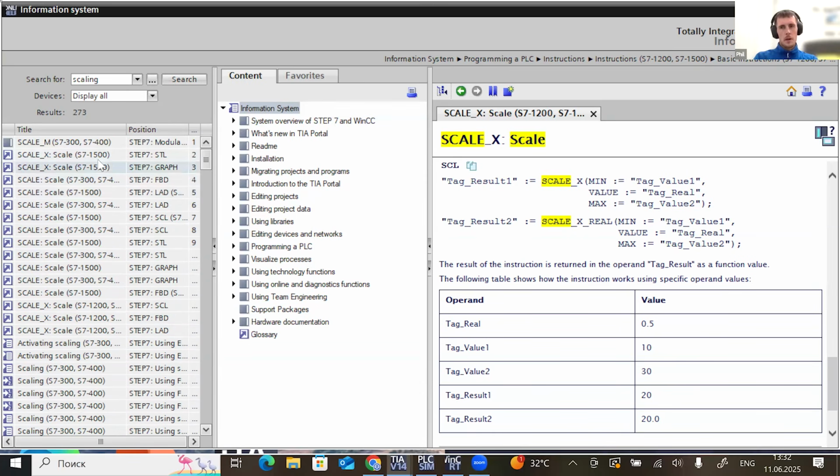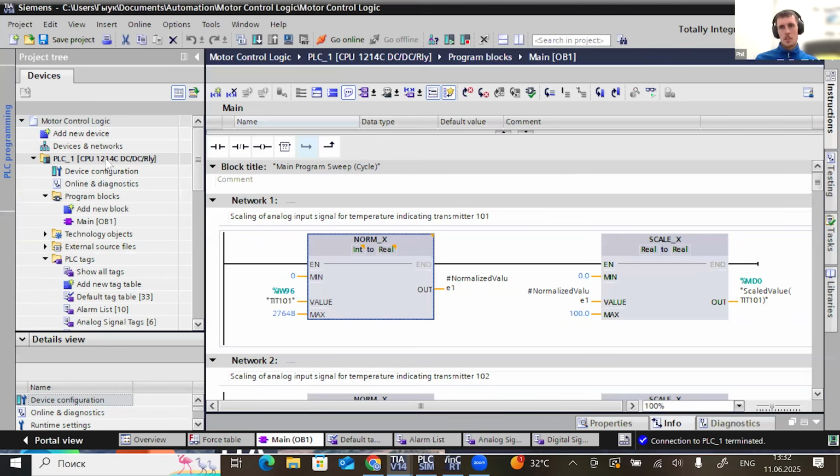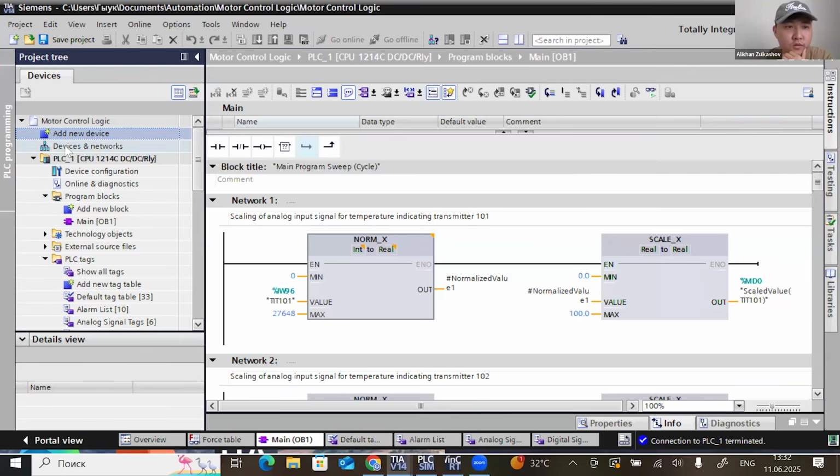Most of the Siemens IO modules actually have a checkbox you can tick in the hardware configuration to detect short circuits and stuff like that, or detect if it's been pulled out. You can actually set it up and then it'll create an auto alarm. You just assign it to a tag. Yes, correct. You're right about this. I'll show you.